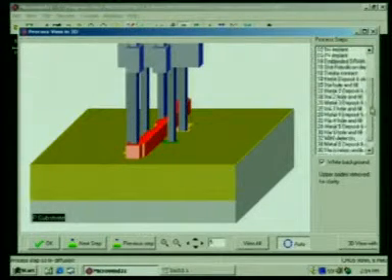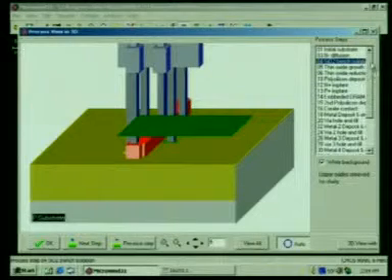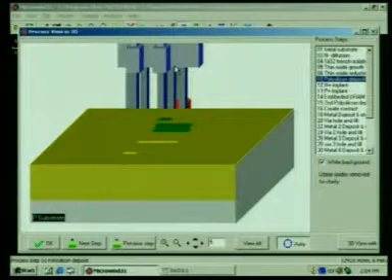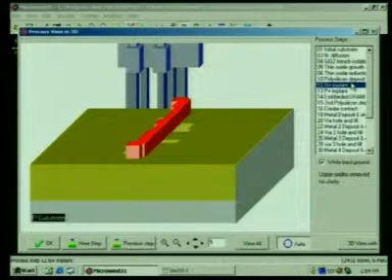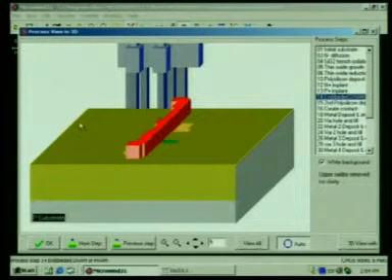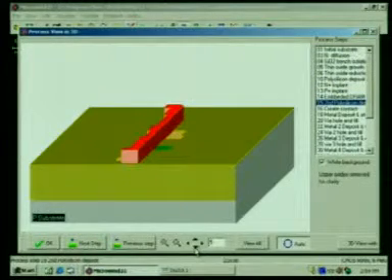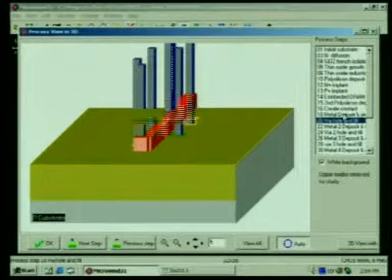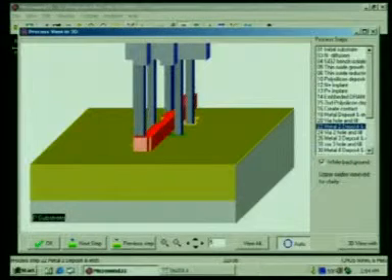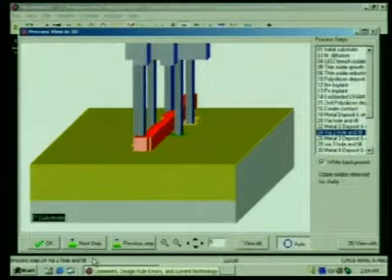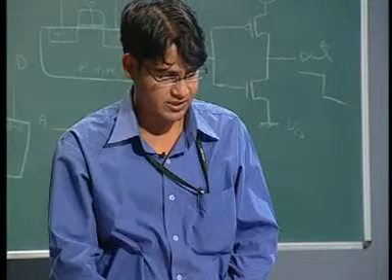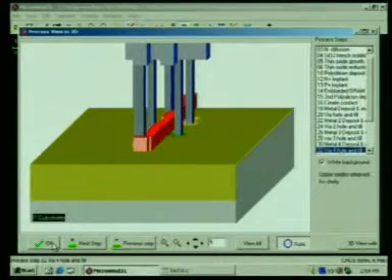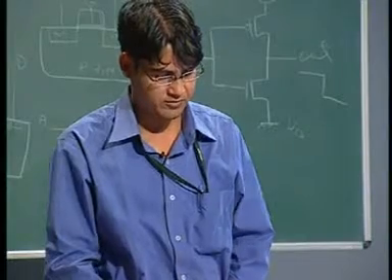These are all the steps needed to design this simple inverter. Actually, I have taken the inverter example. After polysilicon deposit, N plus implant, P plus implant, it will leave out the steps which are not required. So this will give the complete 3D view for your design. This is actually a simple one. For a complex one you need to have that kind of analysis also, the 3D view.